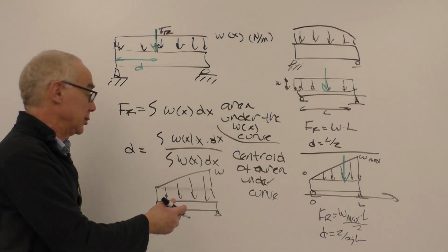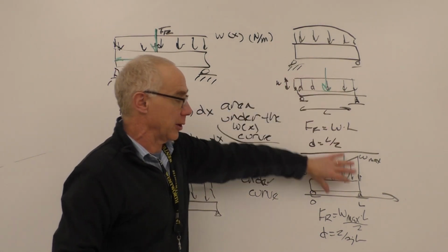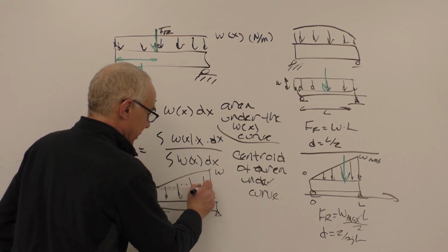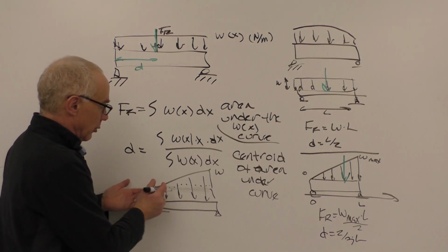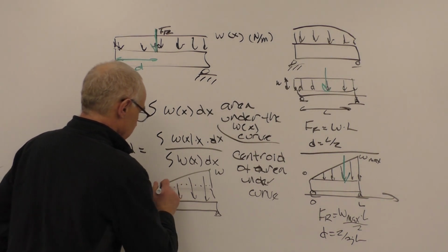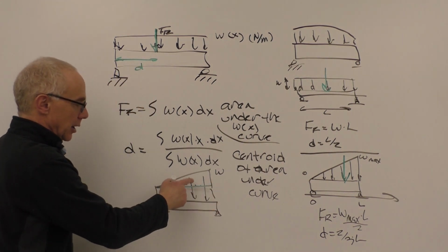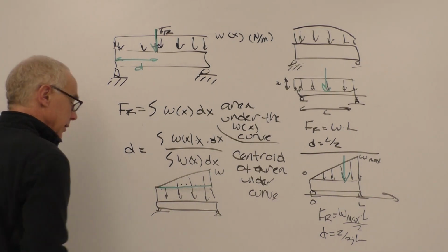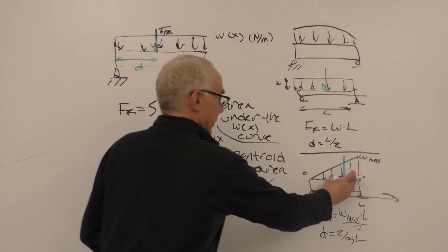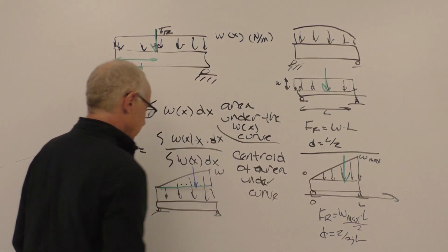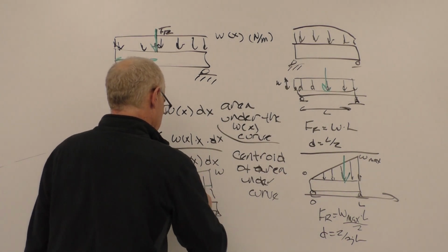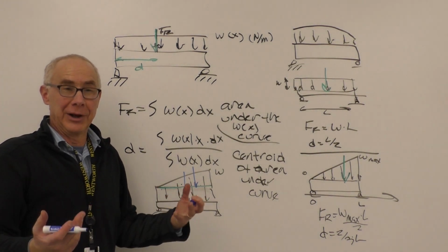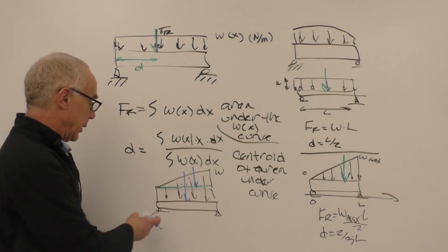We could divide this up into two pieces. So instead of ending up with just one force, like we did here, we'll end up with two. We'll do that by breaking this up into the summation of a rectangular surface below this green line, and then a triangle that goes from the green line up to the upper surface. Then we'll find the resultant vector, like this system, we'll find it here, and for this one we'll be essentially here. Instead of having just one force, we'll end up with two forces. But that's simple enough for me, and we can easily use this to evaluate the support reactions.